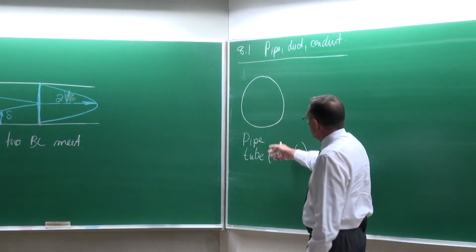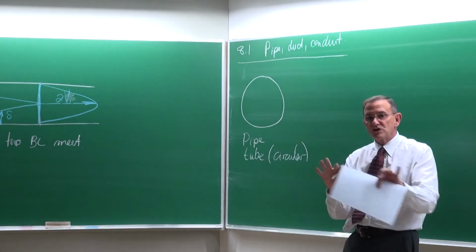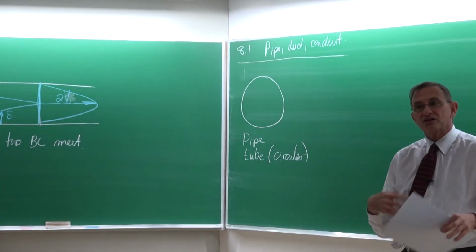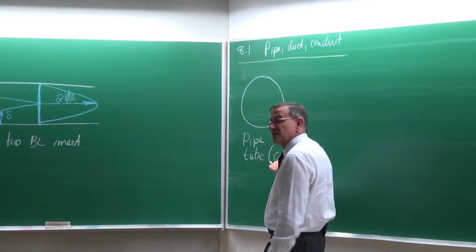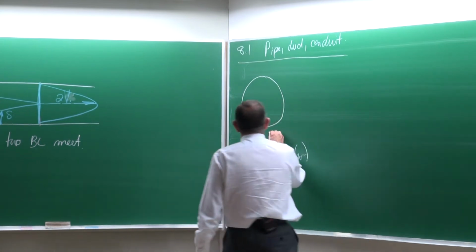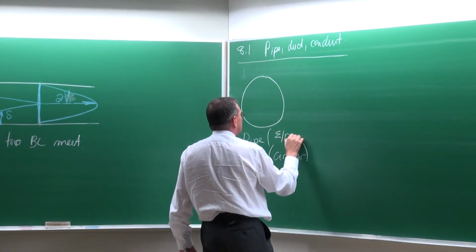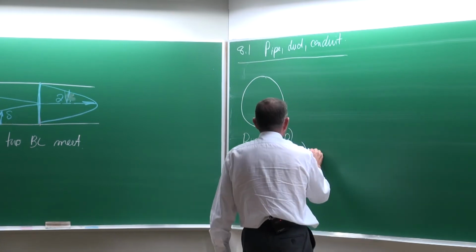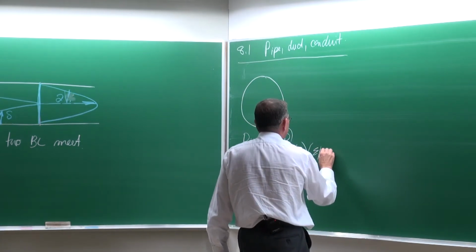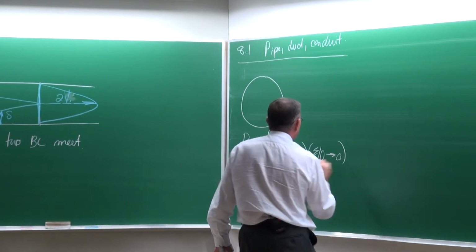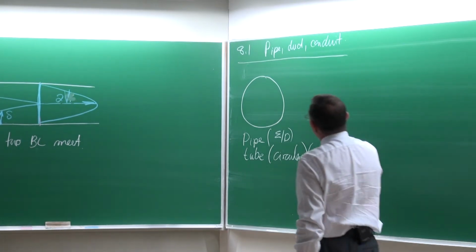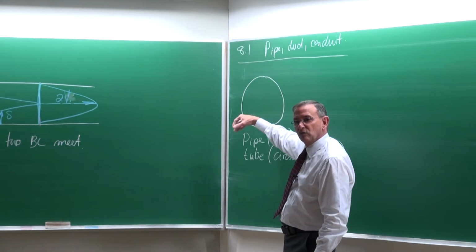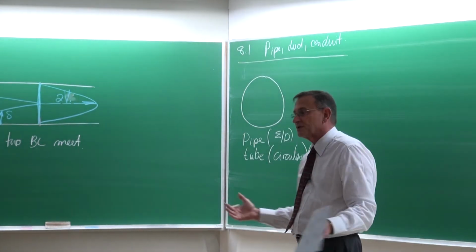What is the difference between a pipe and a tube? Well, the textbook is not very clear about it, but there is some other nomenclature that would say a pipe is a tube which is rough. So the epsilon over D value is significant, while with a tube the epsilon divided by D is approximately 0 for all practical purposes. Then it is called a tube. So at this stage, pipes were casted, and for that reason they started calling it pipes.